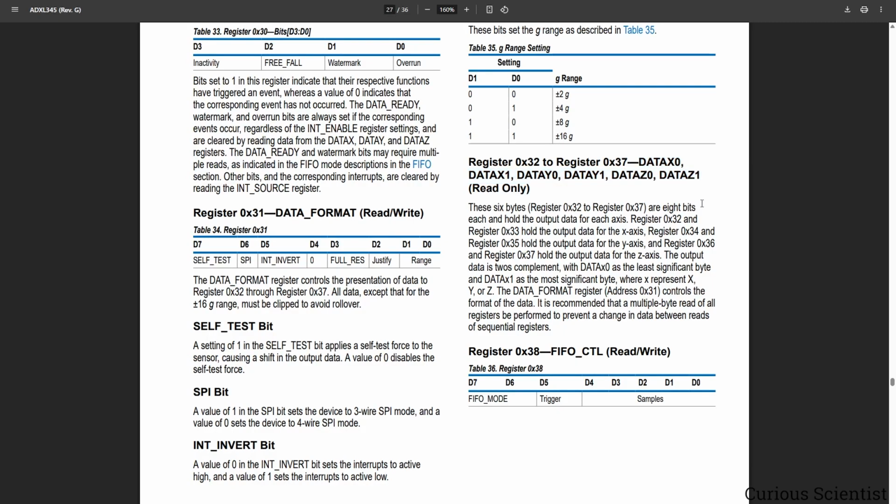And how it works is that since we tell the code that we are going to read 6 bytes, then the MB bit will be set to 1, and then the accelerometer chip will automatically know that after one reading, it has to increment the address and read from the next address and return the data again.